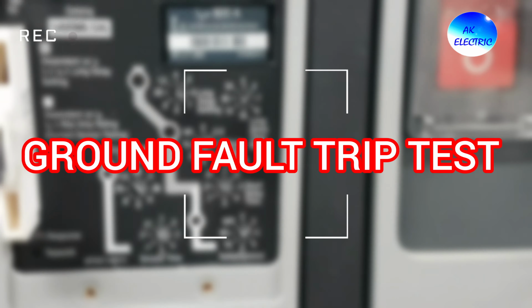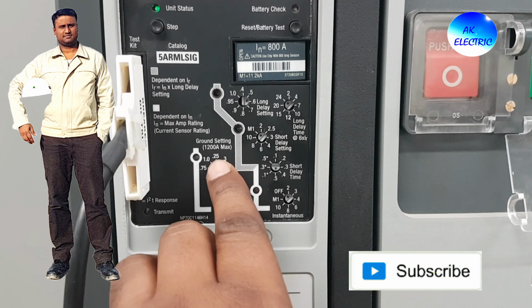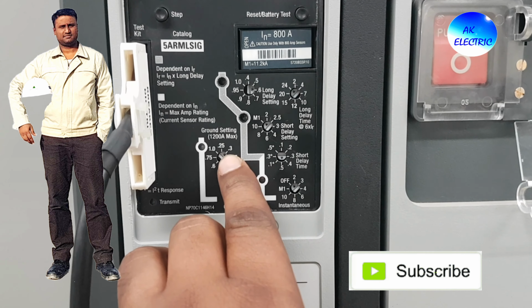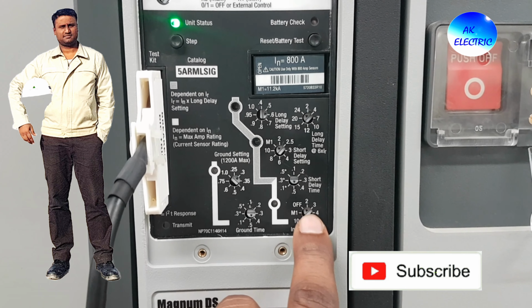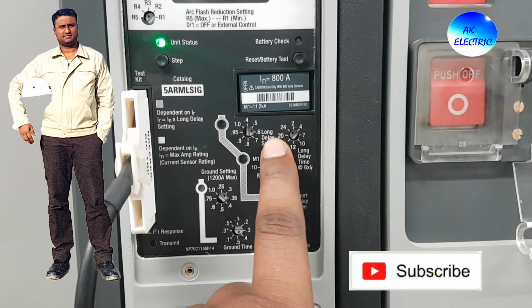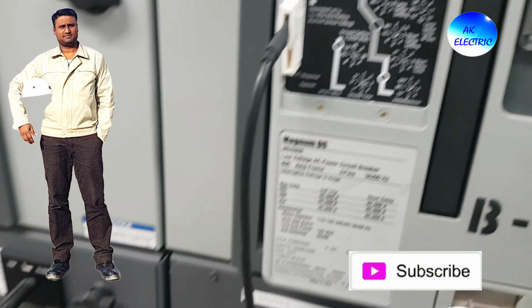For ground fault checking we can keep anywhere, whether it is 0.25 or 0.3, 0.35. Now we are keeping 0.3 and our seconds is 0.5. So all others we put maximum. Instantaneous is off, short delay is maximum, and long delay also maximum. Now we have to check ground fault.